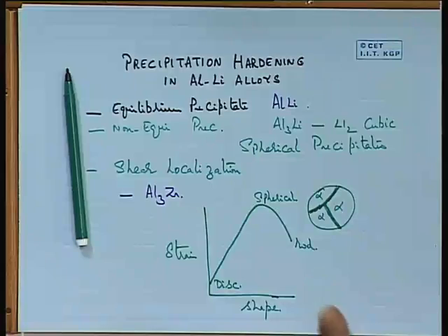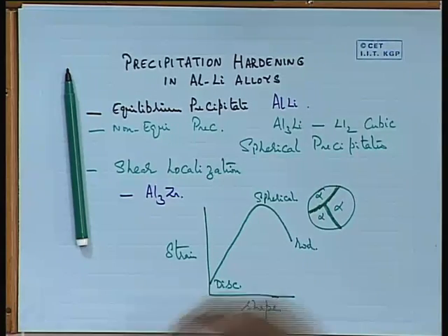In thermodynamics we used to talk about this. So one has to minimize a combination of these two, strain and the surface energy. You can see the disc has the lowest strain energy, but if you have spherical, that will have the lowest surface energy. So how do you have a combination of these two? So that's where what is important is what is the actual misfit parameter.